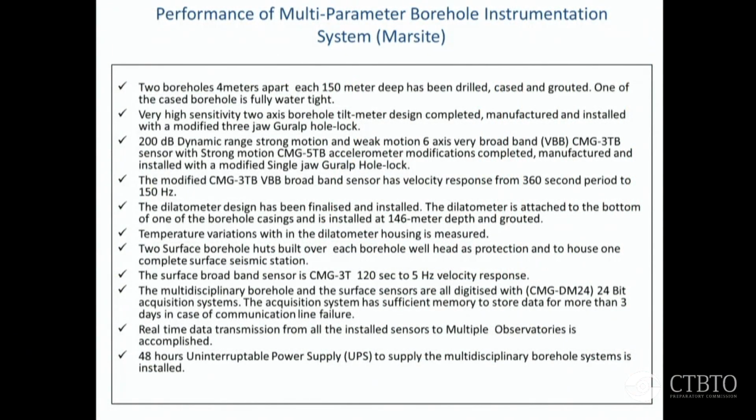The instrumentation that we installed in these 2 boreholes, there are quite a number of them. It's difficult for me to go through all of them simply because of 15 minutes. But we have 2 boreholes side by side. They're 150 meters deep, and they're 4 meters apart from each other so that we can study 2 instruments which are co-located in a borehole, which I don't think actually exists anywhere in the world, as long as someone can correct me.